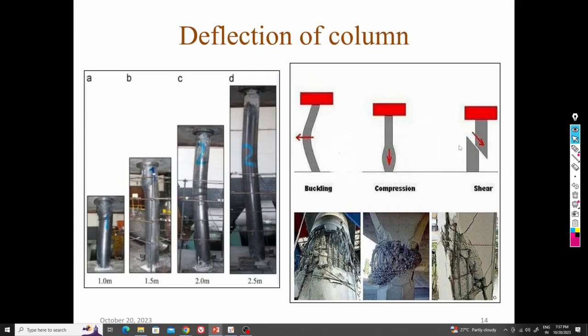Yes, now these are also the same things. This is buckling. So buckling is something we can say is a lateral deflection due to compression. That is buckling. There is a bulging of the column also. The cross-sectional area will bulge like this. See this. So this is not buckling, but we can say this is bulging. This is a kind of deflection only, but it happens because the cross-sectional area is very less and there is more stress in the column, and this will bulge.